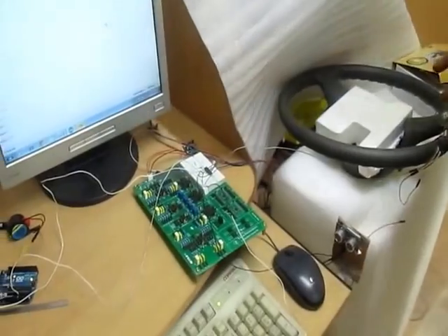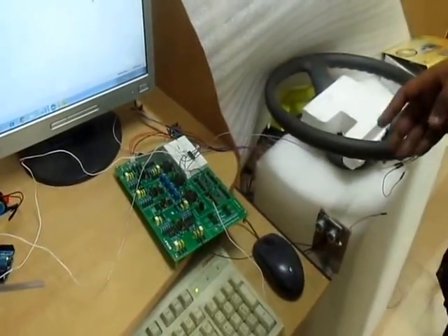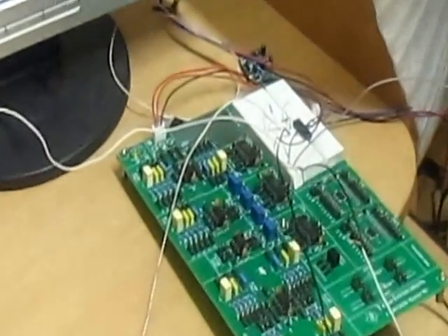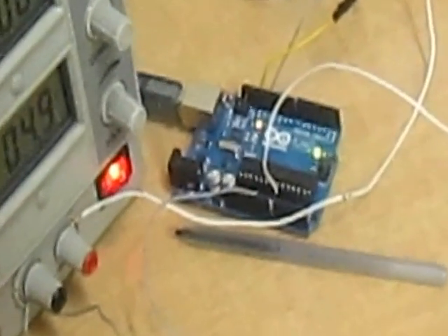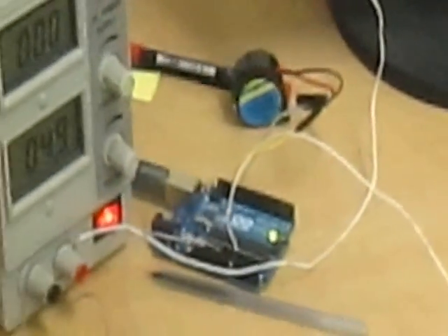Now, from this pressure sensor, the electrical signals are transferred to the amplifier block, where the signals are amplified, and from there on, they are transferred to the microcontroller block, where a threshold is determined for a period of 60 seconds. Now, if the signal is low for more than 15 seconds, then an alarm is raised.